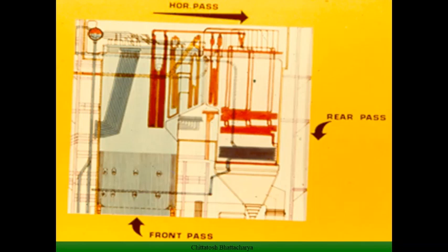So naturally they are important components and they contribute very much to the steam quality and steam parameters. Superheating is done in 3 phases: the primary first part, low temperature superheating, then the primary second part, platen superheaters, and then final superheating.